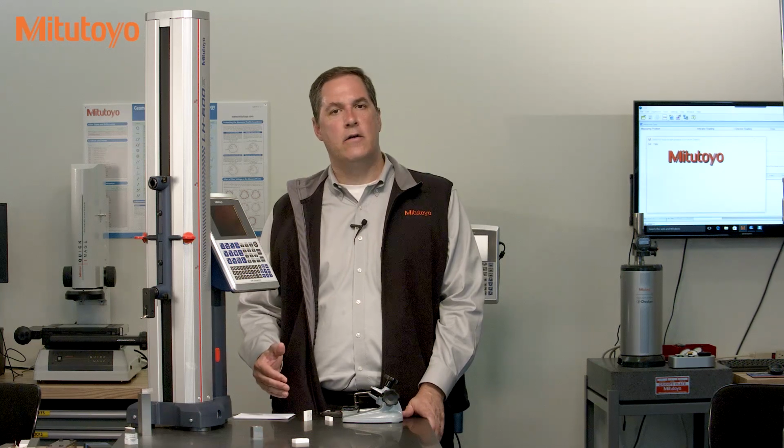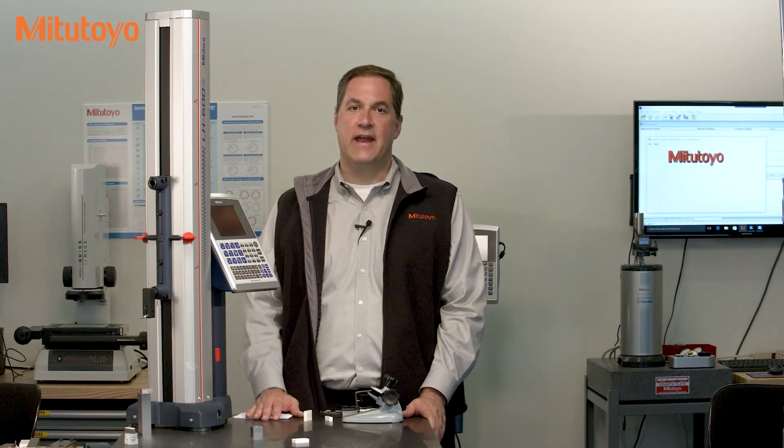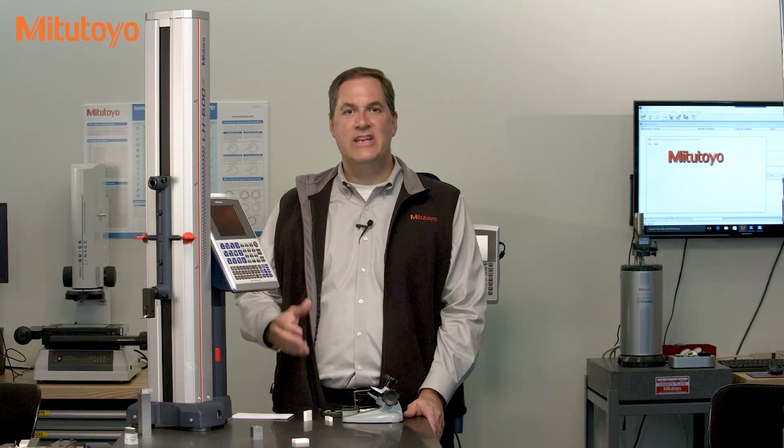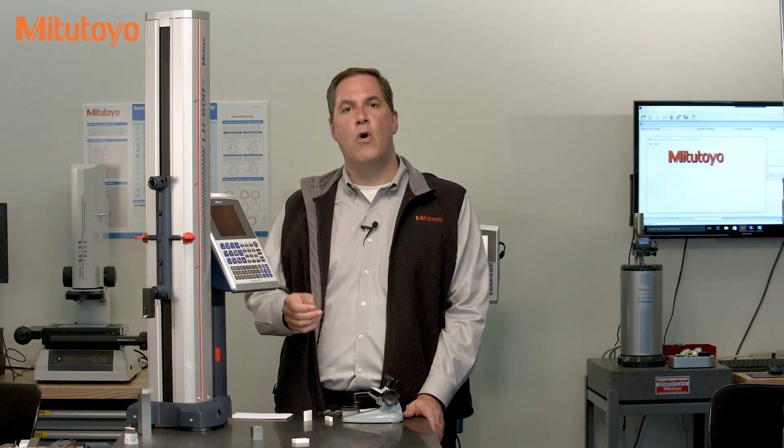So is a TAR around 8 good enough? This is the first question in this episode that I cannot and will not answer. I can teach you how to calculate the TAR, but I cannot tell you what level of risk is acceptable for your organization. I can't even tell you if calculating a TAR is the right thing for you to do. I can tell you, however, that there are a number of organizations that require TAR calculations for calibration work, and that the most common rule is the so-called 4 to 1 rule, or a TAR greater than 4.